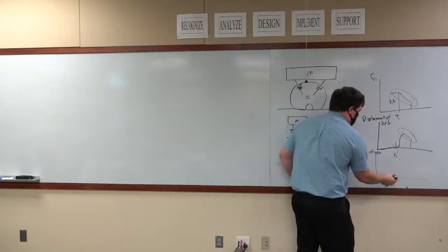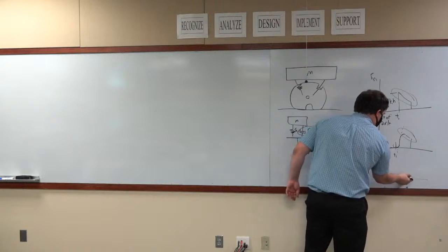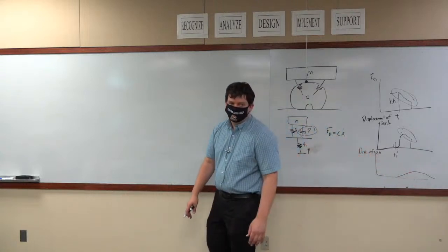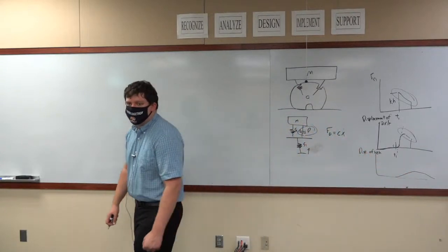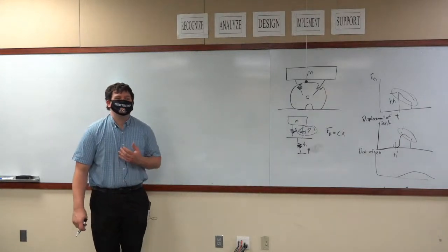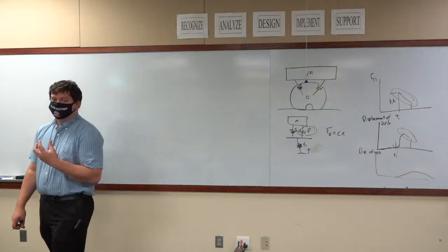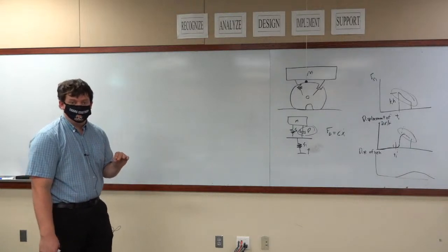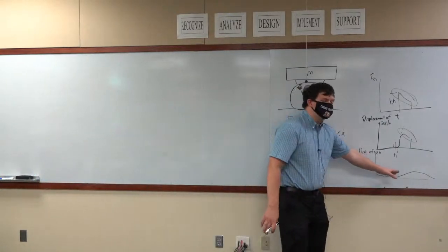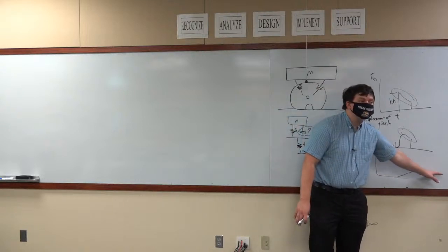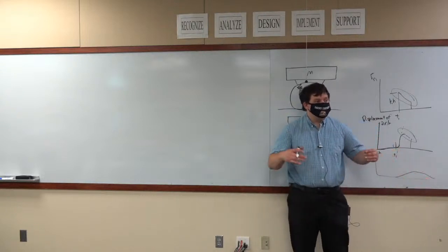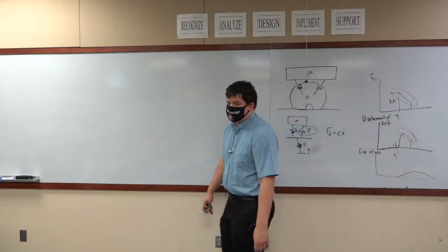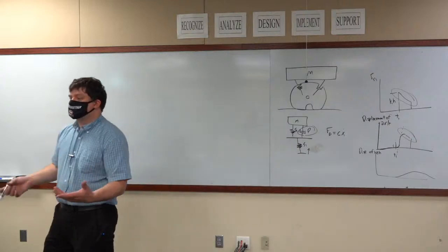And what you want for your vehicle is you may want it to go up a little bit and come back down, but you want it to be very gradual. High impact, when you suddenly bounce up and down, creates an immense amount of acceleration on you as a person, which is extremely uncomfortable. Lower accelerations make people comfortable. If your vehicle very gradually moves upward because it hits a bump, and very gradually moves back downward, that's much more comfortable than having a sudden bump like this. It is the job of your suspension to reduce those accelerations.